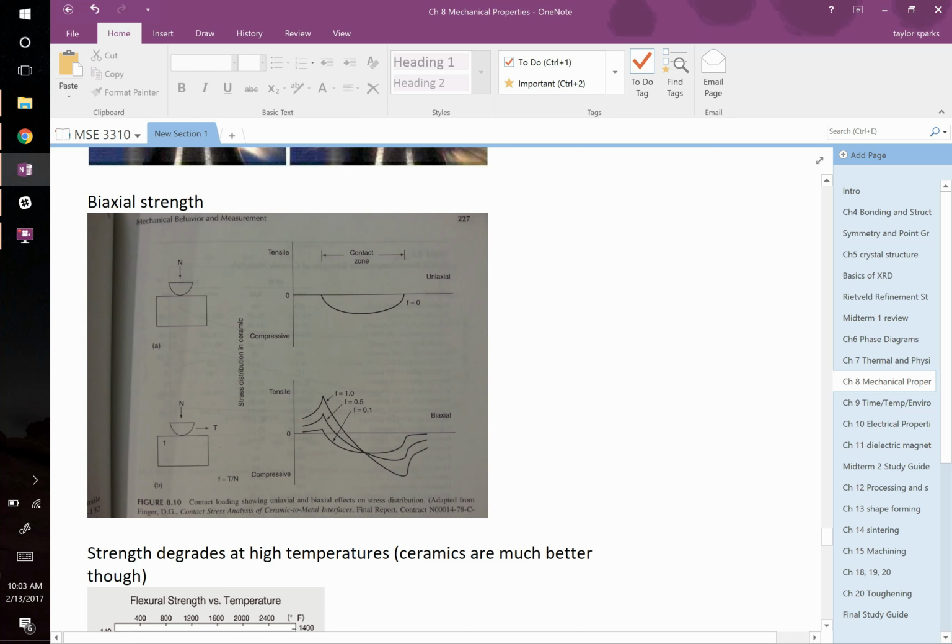So as that piece of silicon carbide on the silicon carbide paper cuts through your material, it's leaving behind it a wake of cracks, probably, because you have this spike in friction. What's the coefficient of friction between a ceramic and silicon carbide? It's going to be pretty high, right? So you can put a lot of lubricants on there, and they run water typically, to try and minimize this post-spike afterwards, but you're still going to have a high likelihood of trailing cracks behind it. So you polish it, and you're leaving behind cracks on the surface. Polishing is a very damaging process when you do it. Okay, we'll come back to that later.